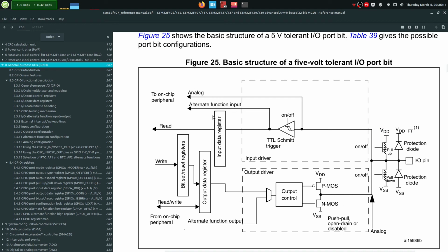You can see all the fancy stuff like here. Let's just concentrate on this part. This is a very traditional thing you're going to see in electronics. This is called the CMOS pair, or the complementary output driver pair, totem pole or anything like that. It's comprised of NMOS and PMOS transistors. So this is going to be connected to the supply, in this case 3V, and this is going to connect the pin to the ground. So this has this hard driving mode, push-pull, where it pushes the voltage out or pulls it down. This is why it's called the push-pull output type.